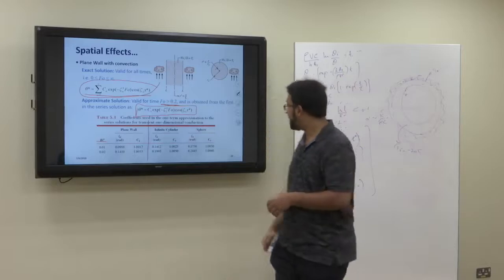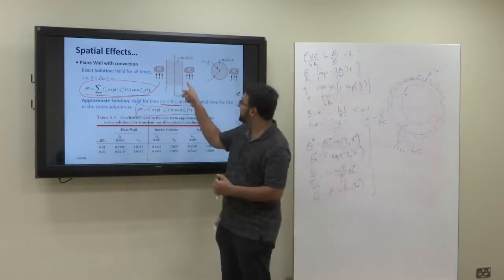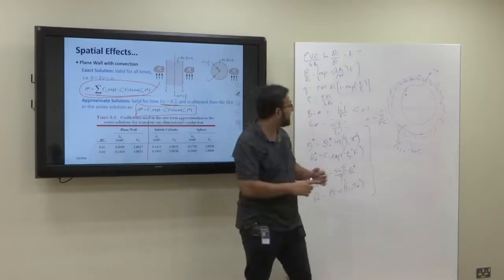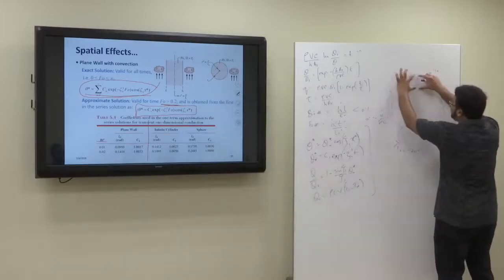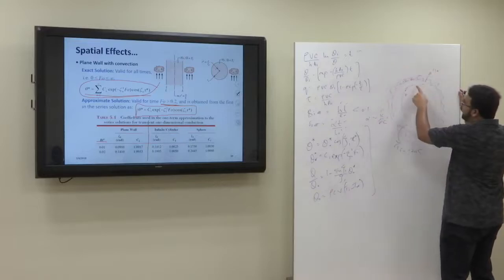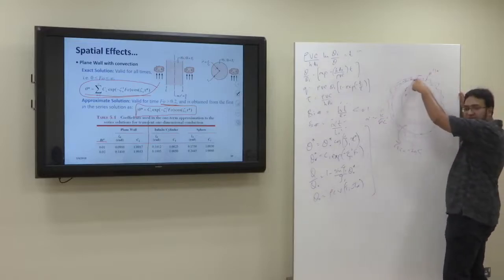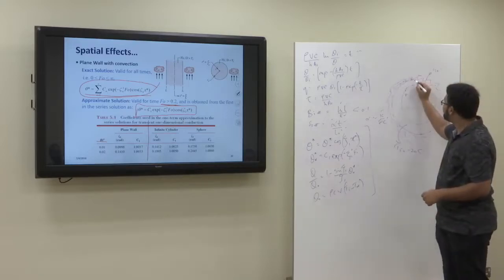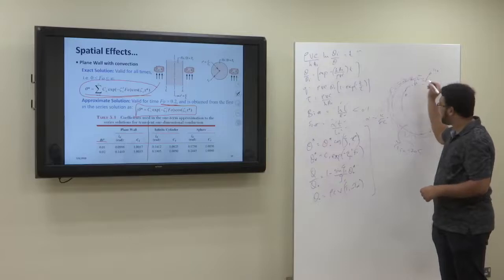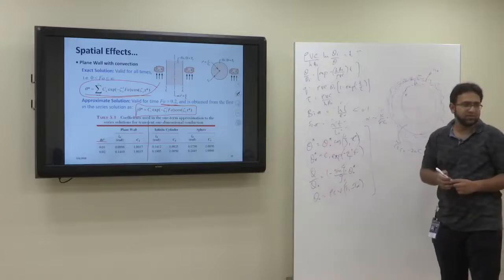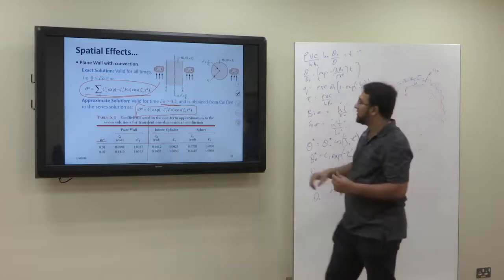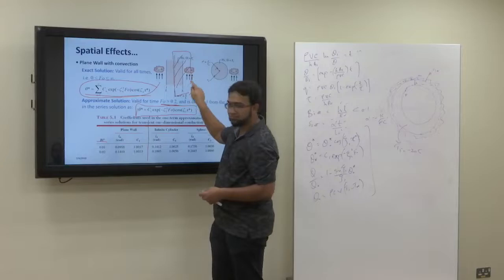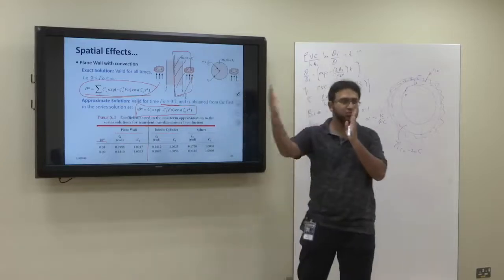Okay, so in this case, although here in the plane wall, our adiabatic was at the center. Now here, if we consider this as a plane wall, if we look from very close, our adiabatic is not at the center. Our adiabatic is here at the top, right? Our adiabatic is at the top, and then we consider that this distance is L, the thickness. So we have here a half case with us, adiabatic at the outer surface.